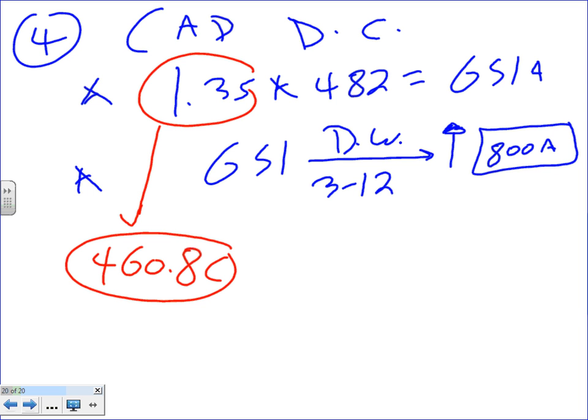I have another table I want you to look at, and then I will do the example. If you look at table 167, please, it will give you typical kVAR sizes, and the size of the conductor, the fuse, and the switch already calculated for you at different voltages. For example, let's look at the 20 kVAR.